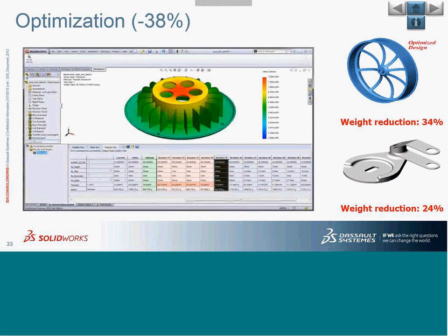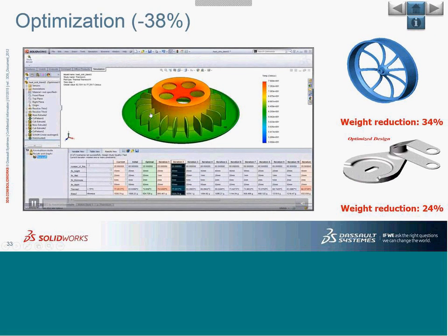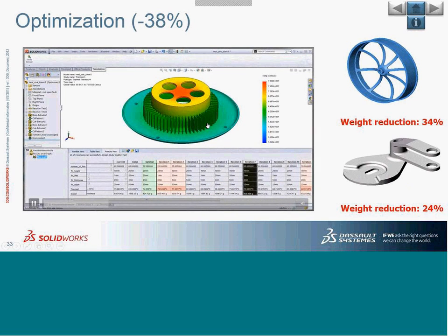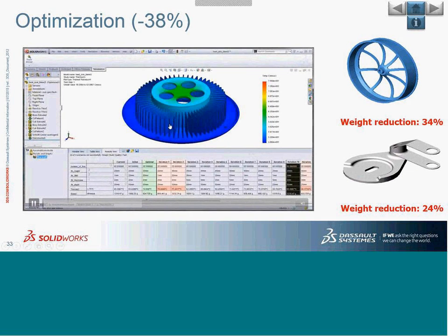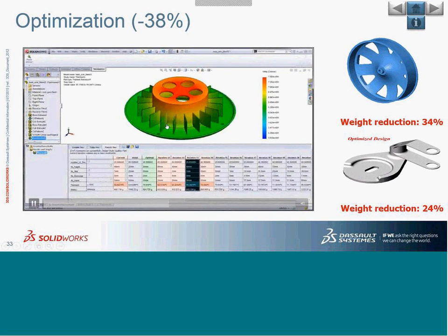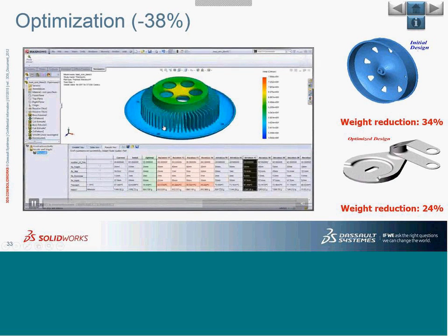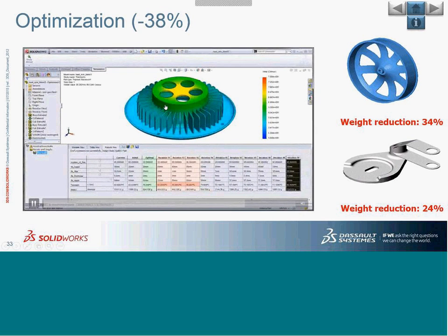For example, in this case, it is basically an LED housing, and I want to make sure the temperatures do not cross a certain limit. I want to design how many pins are required, at what distance, what should be the thickness, etc. So all those finer details need to be understood and conveyed. What is the goal or the final aim wherein I want to reduce the overall mass. So I can give these parameters to the software.